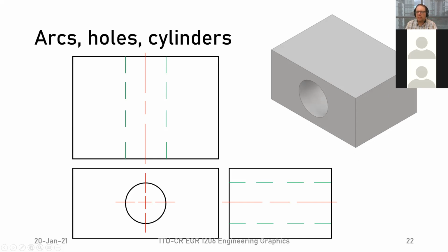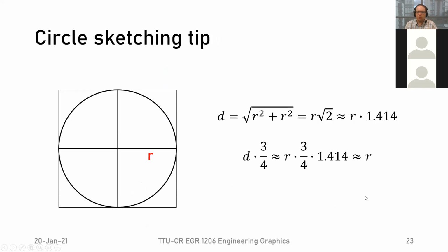So all we'd really see would be the gray box on the side, which is our black outline. But if we're going to look through it, then we see the hidden lines on top and bottom, and then in red the center line. Right? So this is the idea of center lines, and we'll do an example with center lines in just a little bit.